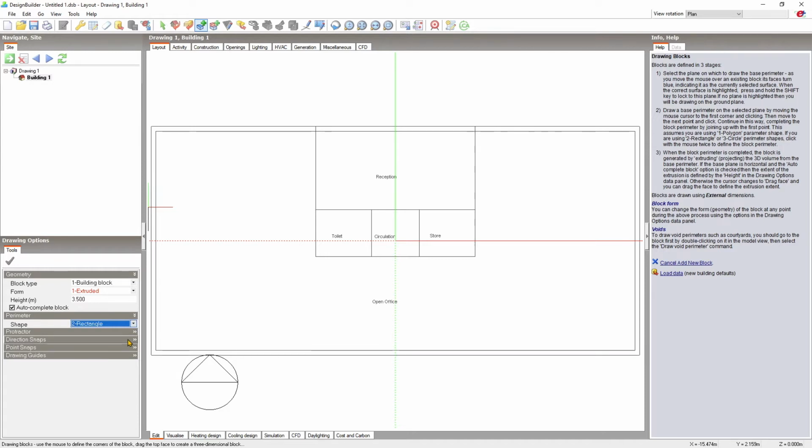You must understand how geometry convention templates work in DesignBuilder before you create geometry, as some codes and standards require you to use different conventions. This is covered in the construction tutorial, so please refer to that if you are not yet familiar with geometry conventions in DesignBuilder. The purple DXF snaps allow me to select the endpoints and intersection points on the plan I just imported.